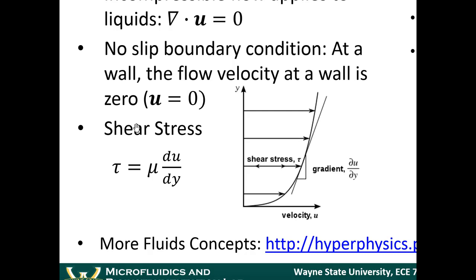Now, think about this. Compare the flow in a large pipe. Compare that to the flow in a very small pipe. What is the difference here? In terms of shear stress, which one do you think is going to have more shear stress? Small pipe. Small pipe. Why would the small pipe have more shear stress? It's more interaction with the outside of the pipe, but inside the pipe. Absolutely. That's exactly right. It's closer to the wall.